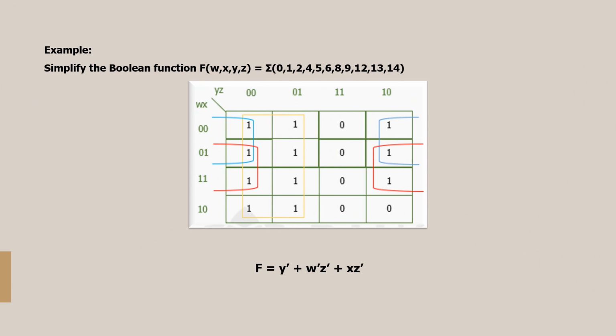Let us have an example for the 4 variable K-map. Here the minterms are given. In these minterms, just represent 1 in each minterm and finally group them and then write the Boolean expression. Here in this problem, we have 3 groupings. One is the octal grouping and the 2 quad groupings.